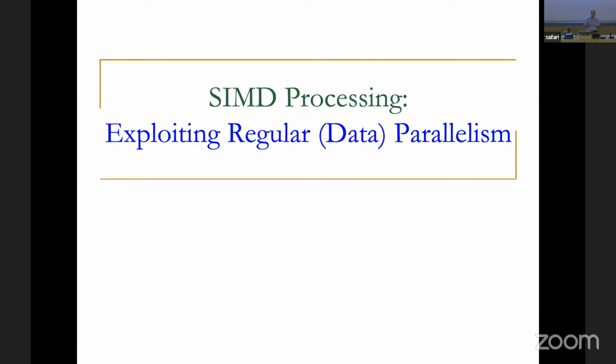We're going to see later in this lecture that GPUs actually make it a little bit easier, and they can also provide good performance even for irregular parallelism. But SIMD architectures are really focused on providing SIMD acceleration. They are more or less useful for regular parallelism.